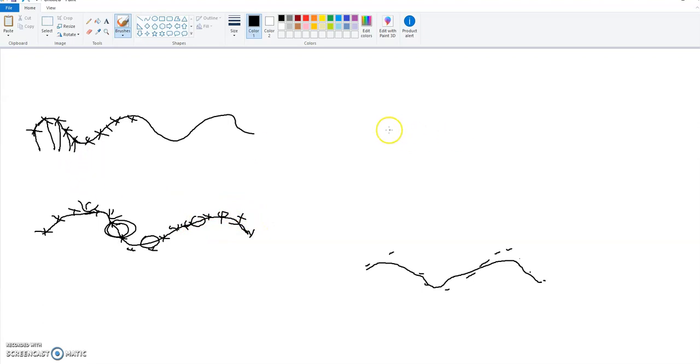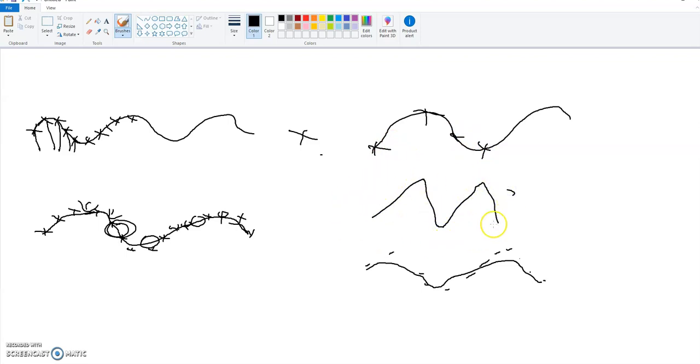So again, if you sample, the Nyquist rate says you must sample at least double your highest frequency. So if this is your frequency and you sample at least double, it means you're going to sample there, there, there, and so on. So your output actually looks, on your PC, like almost a type of square, sawtooth, triangle wave.